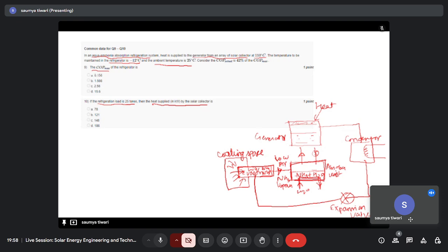Okay, to keep this absorber unit at lower temperature, so more absorption of ammonia into water will take place. Now, from this rich solution, the next step is the desorption that occurs in this generator. So here we get our basically strong ammonia water solution. At this point, after getting our rich mixture, we have here your strong ammonia water solution, right?